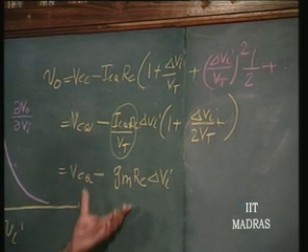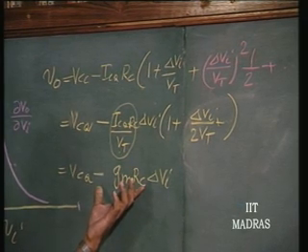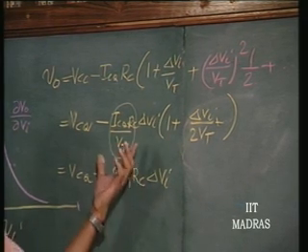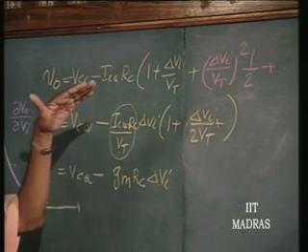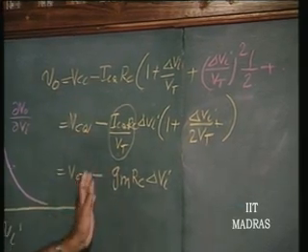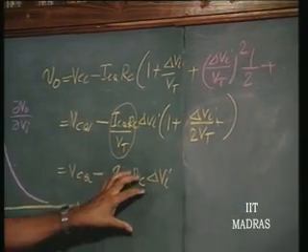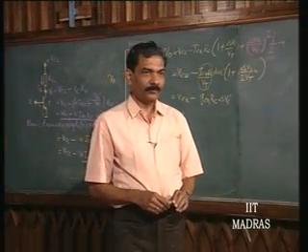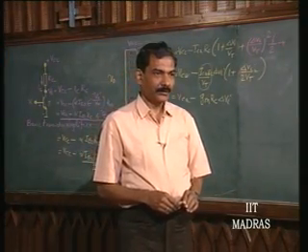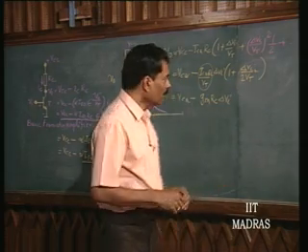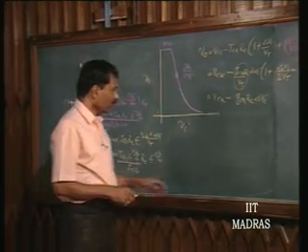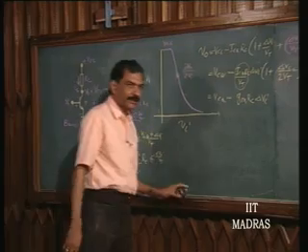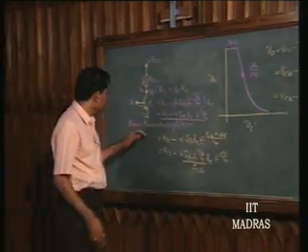So, you can see that phase shift coming about: when Vi increases, the collector voltage is decreasing. So, you see the phase shift of 180 degrees and also the gain of Gm into RC coming into the picture. Okay? This is clear. Now, this amplifier is not good enough for us. Look at the problems associated with this amplifier.